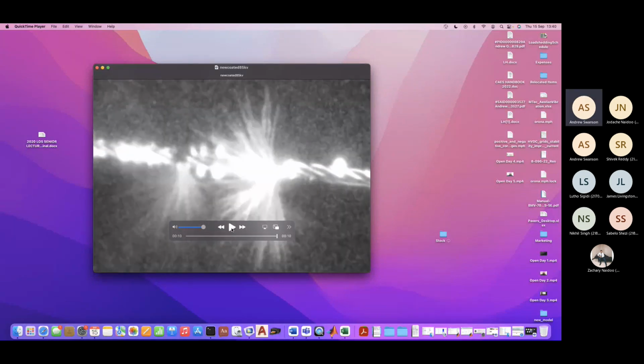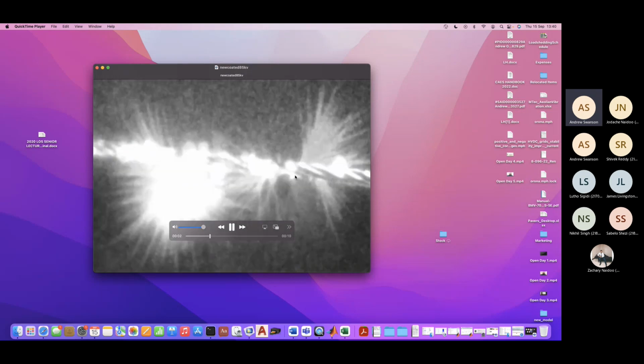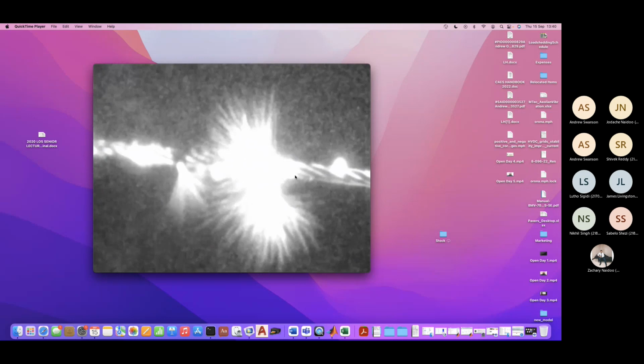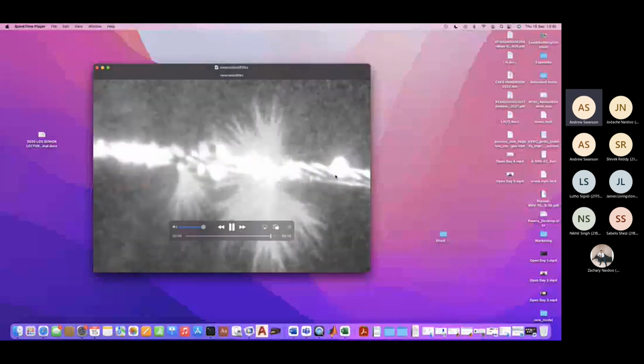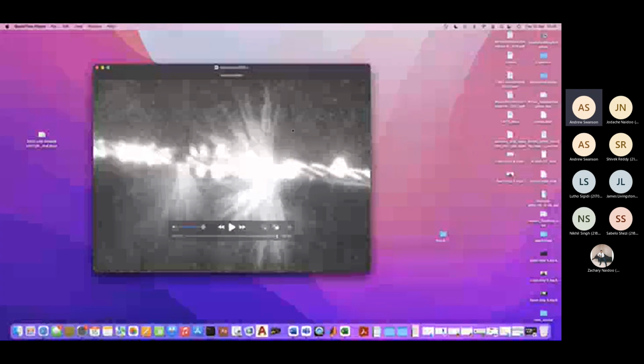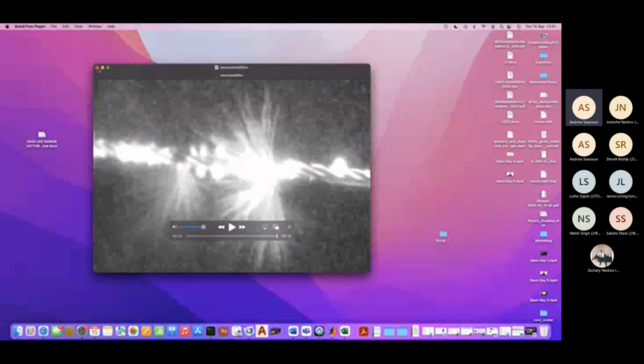Now if you recall the practical, it was kind of a crackling sound all the time. You can see those discharges occurring, and that leads to that crackling sound. You can see it's all around the surface of the conductor. A little bit further away, there's not much going on. Okay, so that's corona. We need the right voltage or the right gradient for that to occur.